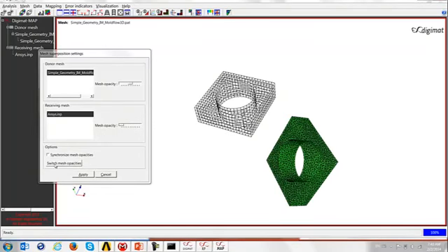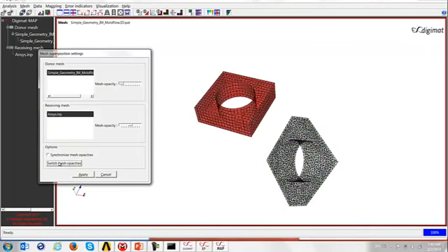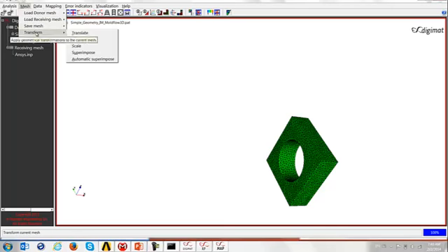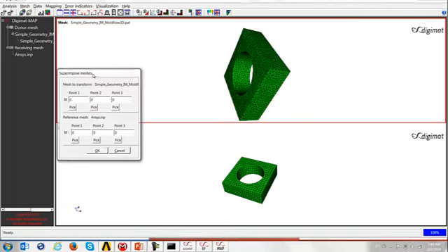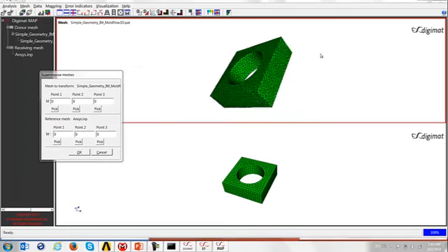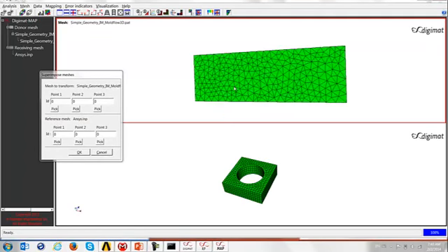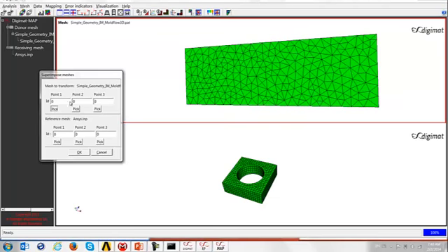So what I see here is that indeed I have dissimilar arrangement of the two models in terms of position in space, but also in terms of orientation. So I go to a transformation tool where I can superimpose both meshes. And basically what you can do here is you can pick nodes and superpose the nodes to be able to rotate and translate the meshes in space.